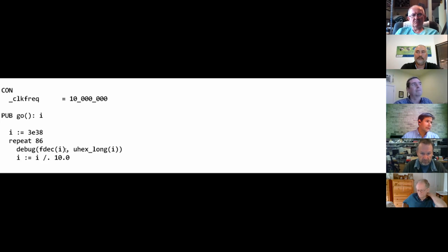I'm playing around with an online IEEE 754 converter, just messing around. Usually the exponent bits are set with most floating point numbers you're going to work with. So that's a quick sign: if the number, interpreted as powers of 2, is an integer, then that number is in the hundreds of millions. And that usually isn't something you're dealing with on a regular basis when you're dealing with integers in typical microcontroller applications. So that's a quick sanity check to see if the user's intent is probably to make it a floating point number, or whether they're treating it as an integer.